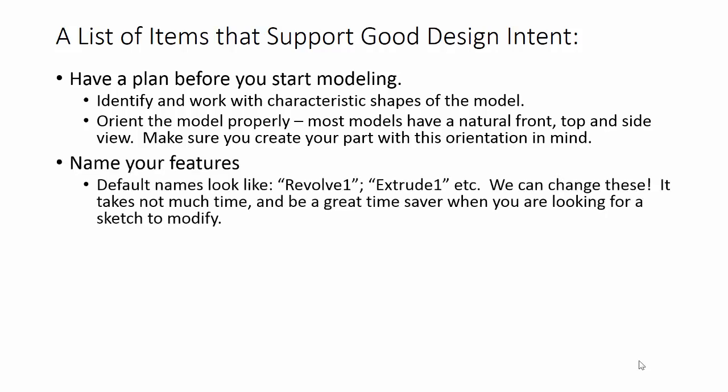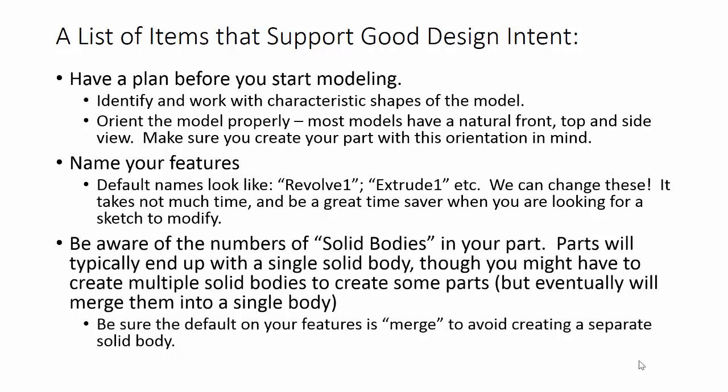It also is good practice to name our features. SOLIDWORKS assigns default names to features like Revolve 1, Extrude 1, etc. But we can change these, and it does not take much time. It can be a great time saver when you're looking for a particular sketch or feature to modify.